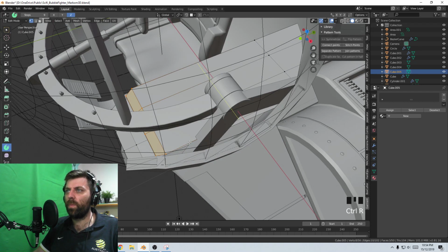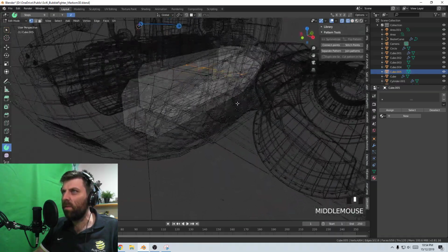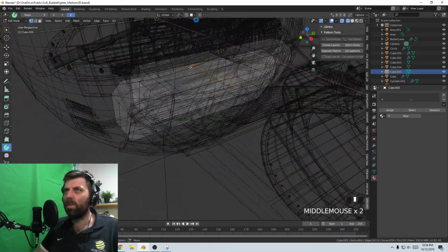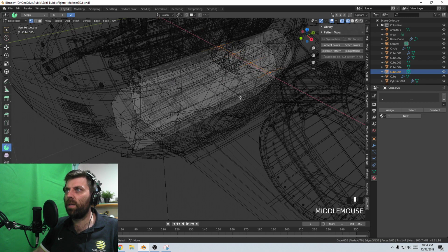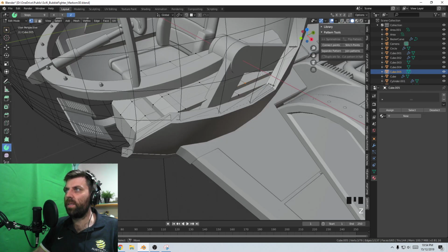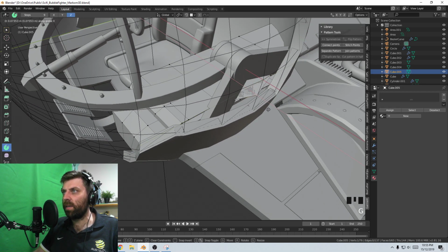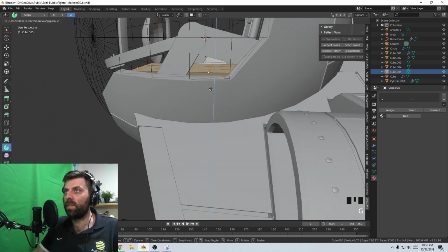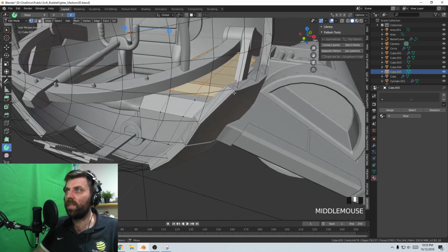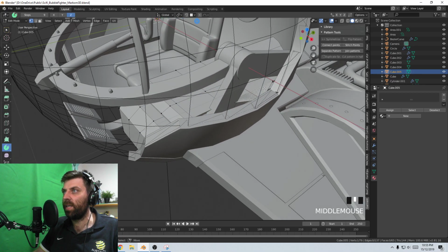And we've got a problem here. So I'm going to put an edge loop in here. Edge loop in here. No, that's the wrong area. Edge loop here, here, and here. So I can grab these three. GX. Oh, that's too high. Control L, G, Z. Bring that down a smidgen. GY. So I'm just trying to hide everything underneath.